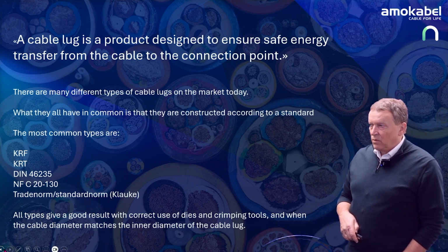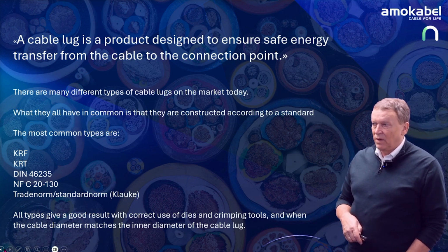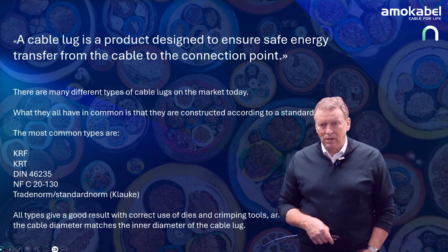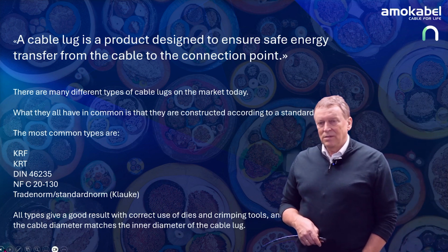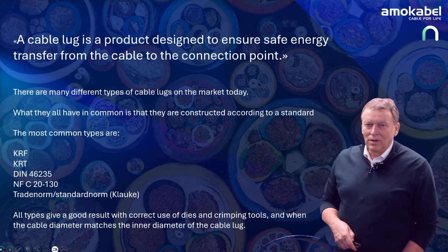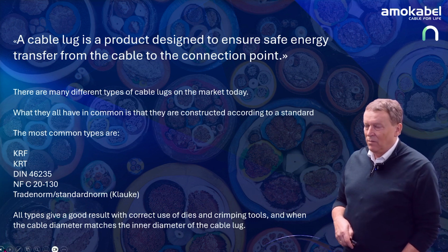All types give a good result with correct use of dies and crimping tools, and when the cable diameter matches, very important, the inner diameter of the cable lug. So there's no bad lugs, it's only bad connections, and you as an installer need to be sure that you're using the correct cable lugs for the cable that you want to use in the market.